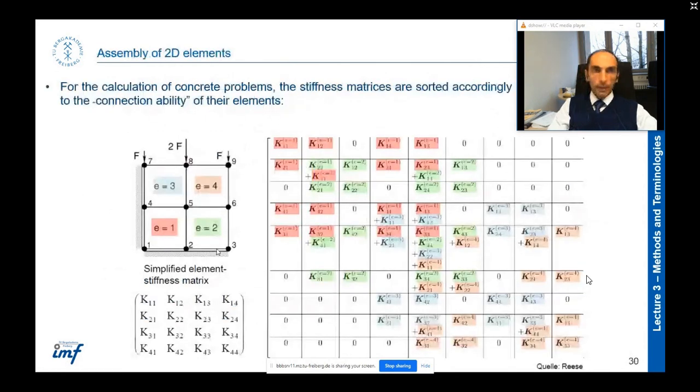Okay, this is about the stiffness matrix. You can see that just in this band in the middle, you have the value for the stiffness, and at the corners usually you do not. This color shows that, for example, node 1 is connected with node 2 and with node 4, but it's not connected with other nodes. So the color shows the connection between the nodes.